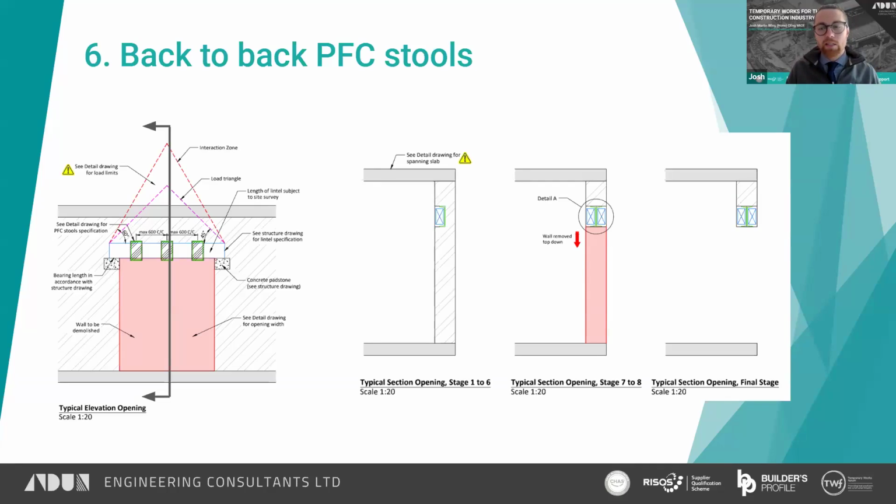However, as this is a sequence that allows multiple lintels to be installed side by side, one side is usually completed before the other to ensure that the wall receives as much support as possible throughout the work. So here's what we do. We break out pockets, carefully, and then install the stools on one side only.